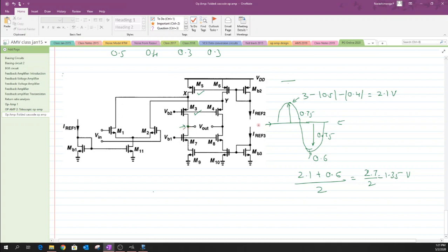and this common mode voltage is being applied as its input, through this unity gain feedback, it has been applied over here. So which means that this 1.35 volt has to be split as a voltage across the gate and source of M2 and the VDS of M11. And we want this VDS to be the minimum, and that minimum value would be equal to VOV of M11. So we want to have a split of these values,